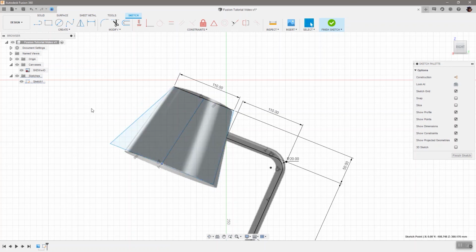The symmetry condition is going to happen through geometric proofs. I can actually use the symmetry command if I so wish. I could say escape, and I could say symmetry. You, dear line, are symmetrical to this line about this line. And that will actually achieve what I want, and then I can sort of pull things back into the shape that I want.